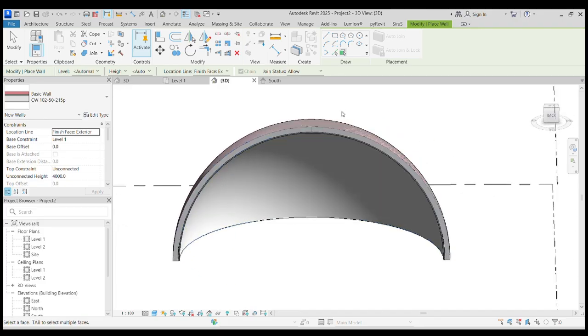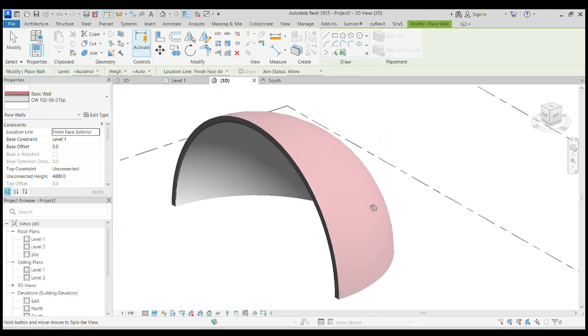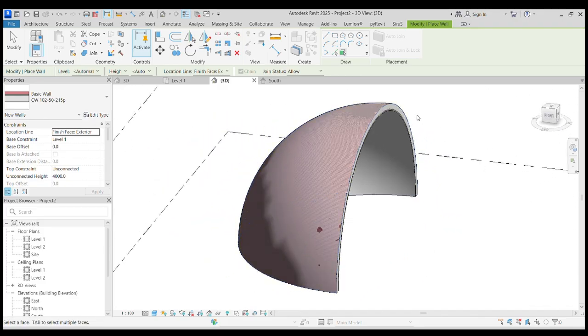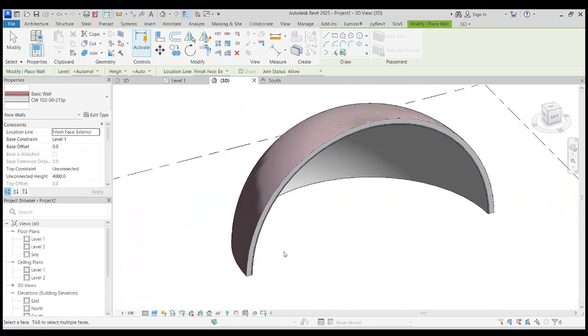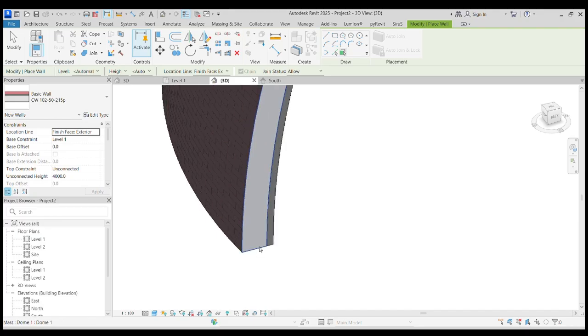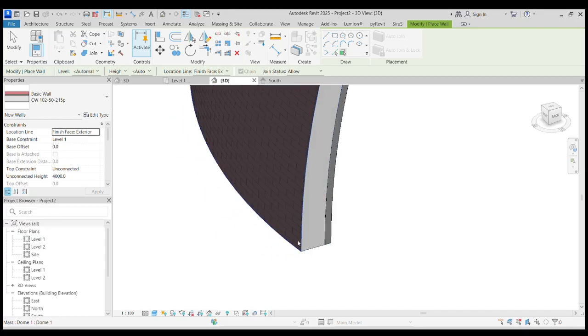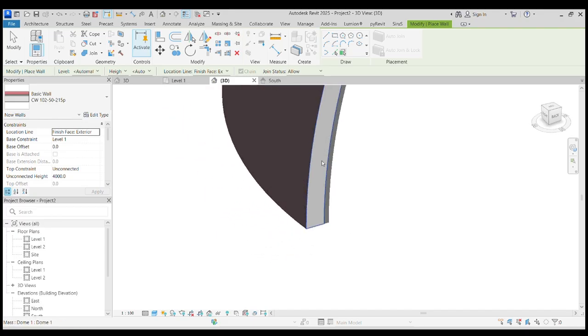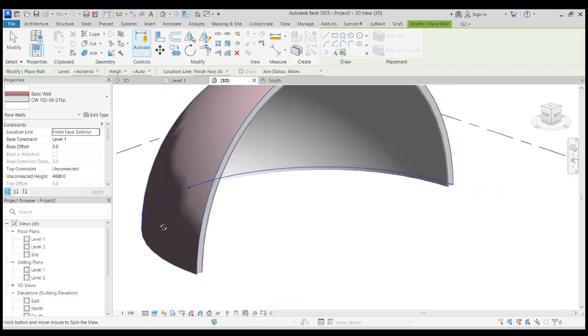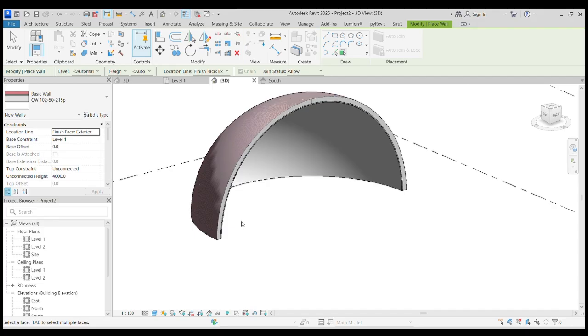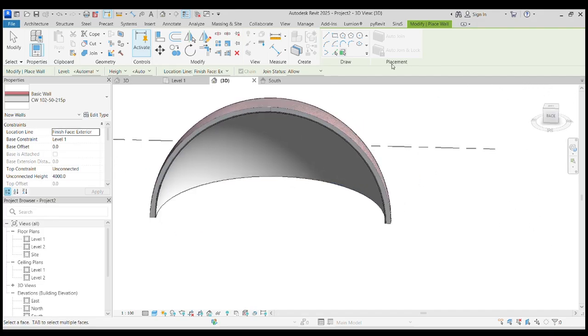All right, and then pick faces. You pick the exterior face and look, voila, looks neat. And as you can note, we got rid of the problem of the thinning here. The section is continuous throughout the geometry of the shell.